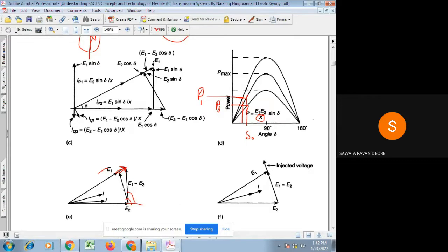So a significant change in the phase angle of the voltage drop across the transmission line occurred because of changing the magnitude of one end voltage of the line. Because of this change in phase angle, the current flowing through the line has approximately the same magnitude, and only the phase angle of the current phasor has shifted.